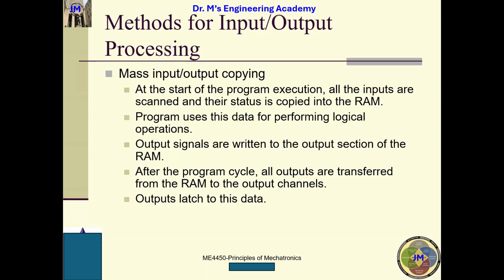You can see all these inputs come into the input image table. After I finish the logic checking, the output image table at the same time drives the different output devices. Questions so far?